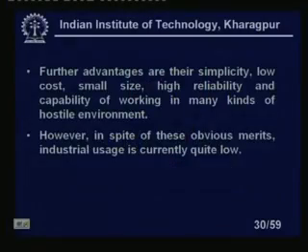Even though the potential is quite high, there is some vicious circle. The people who were using conventional pneumatic sensors in the process industry, these were not new. When the electrical system came, converting the 3 to 15 psi control signal to 4 to 20 milliampere, there were also long objections. But slowly, over the decades, we found all these pneumatic systems were replaced by electrical systems, where the current is 4 to 20 milliampere. Similarly, we also hope that in future this will all be replaced by fiber optic sensors.